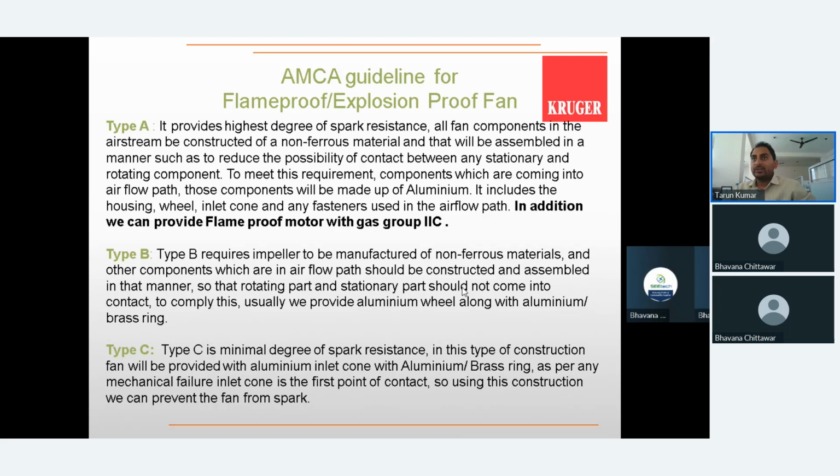For the smoke exhaust fan, the motor is made for 250 degrees centigrade for 2 hours, which can be used only for emergency and fire application. Whereas the spark resistance kind of motor is made for 50-degree temperature, just to avoid the spark. If you see the frame size of the motor, it will be a little bit bigger than the normal motor, since the rotary part inside the motor is kept at a little distance.